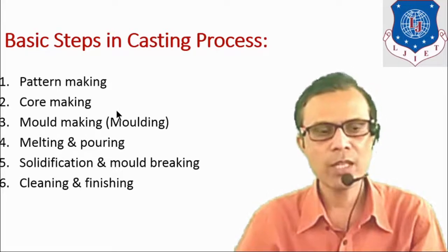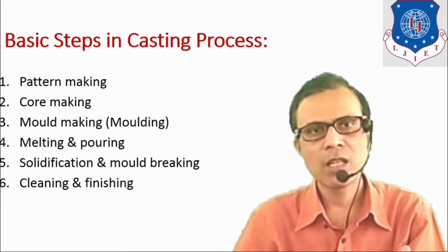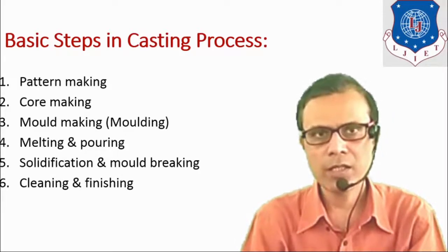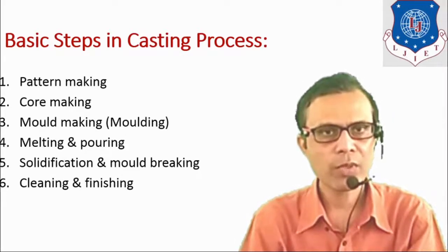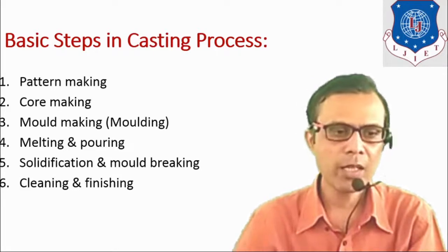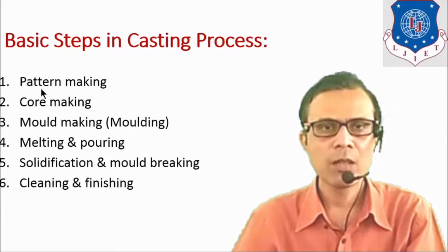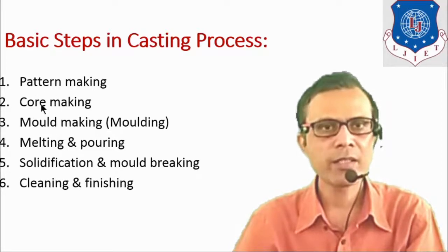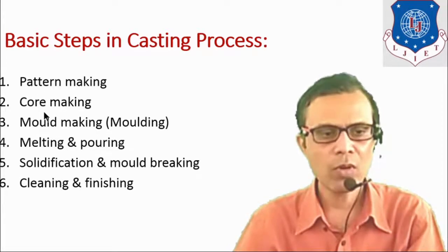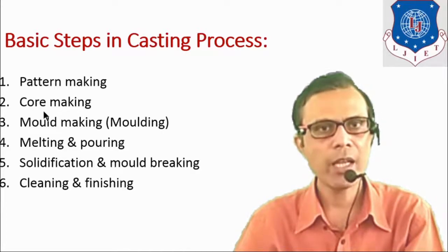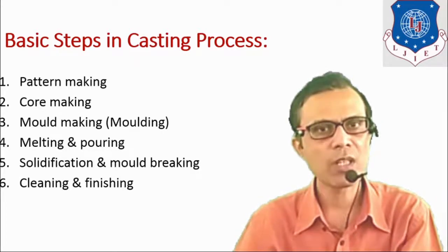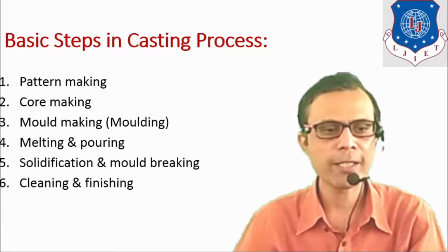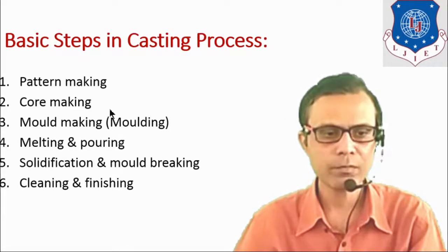So actually, what is the difference between pattern and core? Both are the cavities which are useful to produce a casting, but pattern is removed after the molding is completed and core remains inside the mold cavity. So always this core will remain in contact with molten metal. So it is subjected to high thermal stresses and high temperature.